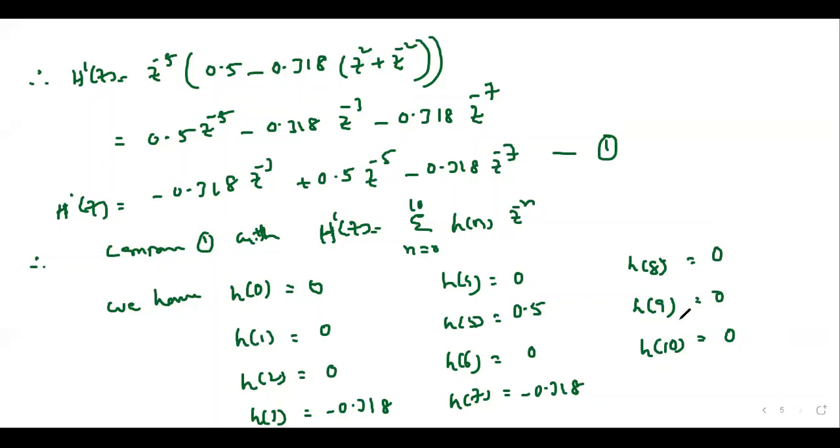These are the finite impulse response values, FIR. Now, based on these values, is it symmetric or anti-symmetric? Symmetric, sir. So therefore, h of n is symmetric and n is odd. Correct?